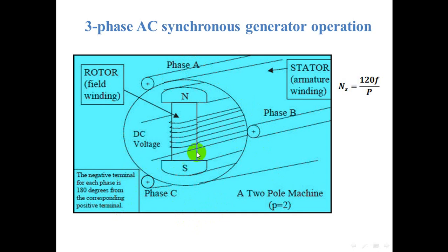If the conductor is rotated in a clockwise direction for another 90 degrees, then it will come to a vertical position as shown in the figure below. Now the conductors and magnetic flux lines are parallel to each other, and thus no flux is cutting and no current will be induced in the conductor.